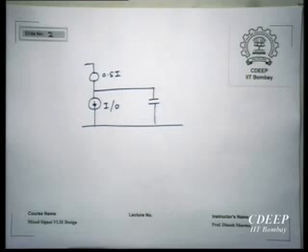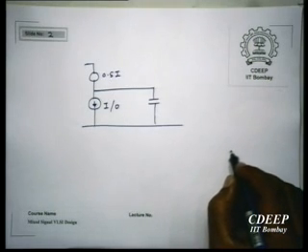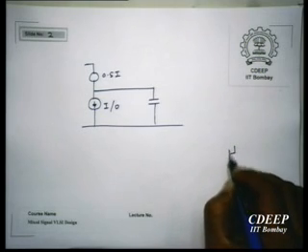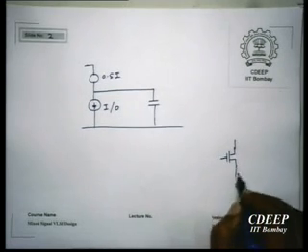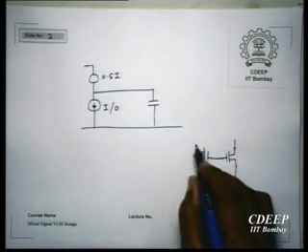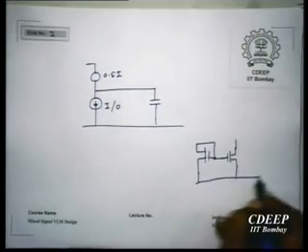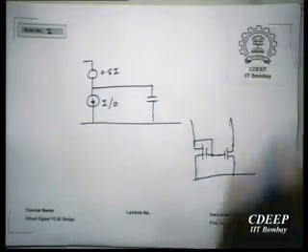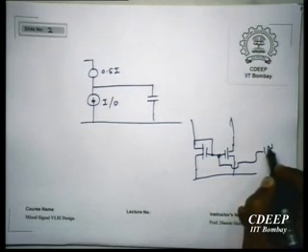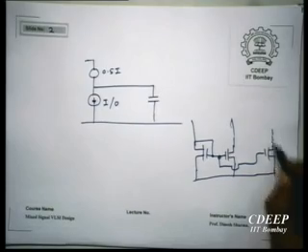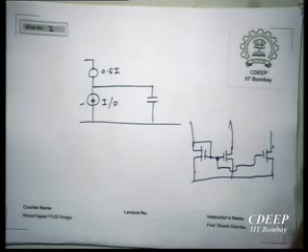And notice that the rest of the interconnect design doesn't change at all. Even the beta multiplier does not change. Okay, what changes is the current multiplication ratio in the current multiplier. Okay, recall what we had was that this is that beta multiplier final n channel transistor. These are the two n channel transistors. This is the beta multiplier. Okay, the corresponding p channel transistors on top. So what I do is I take this voltage out and now put a transistor here. So this is my current source, this one, and I put an IREF here.